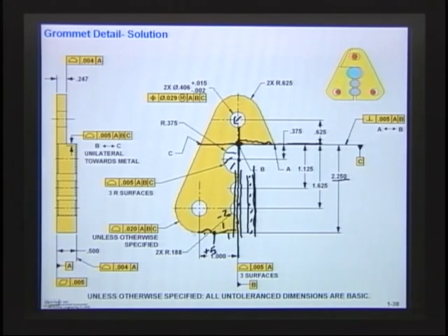See that outside radius? They could come over and set their 0 on the basic dimensions. See that 1.625? They're going to come at that 1 inch to come over to that spot. Then they could come in and they could probe where this surface is. If they want to find out where this surface is, they could do the same thing. Set their 0 over here and then probe that surface. Right? That's how they're going to be looking at it. So the profile tolerance is just seeing how much it's off its spot. Right? All right, that gives you a little idea, a little insight into the inspection.